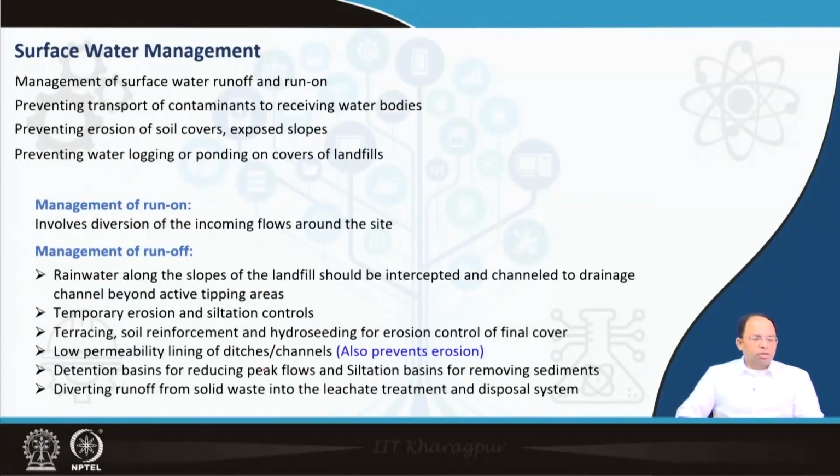Now we come to surface water management. So we have got landfill gas management, landfill leachate management, but we also need to manage the water that comes into the landfill. Particularly we are concerned with the surface water, and the surface water could be both runoff and run-on. Run-on is the water which is moving from the surrounding area over to the active landfill site. So we want to prevent that.